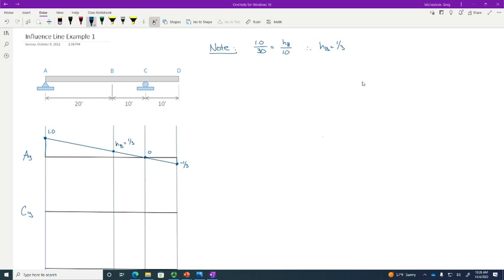2 vertical reactions, right? And the sum of those reactions must be what? Well, the sum of the forces must be 0, but if we're always applying a downward load, then the reactions have to add up to be 1. Does that make sense? So before we draw anything, what does the value need to be right there? 0. What about right there? 2/3. 1. And 1 1/3, or 4/3, right? So that means our influence line needs to go like that.